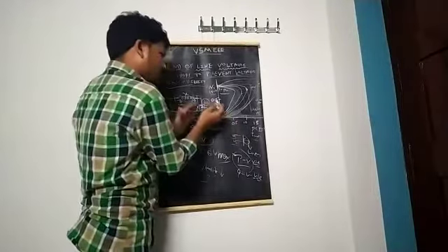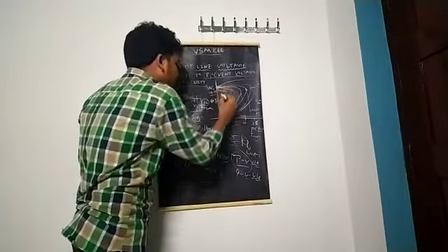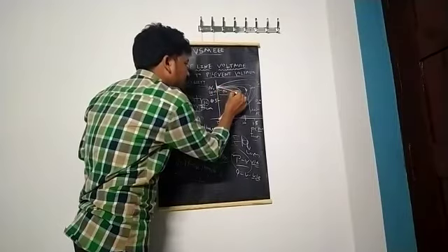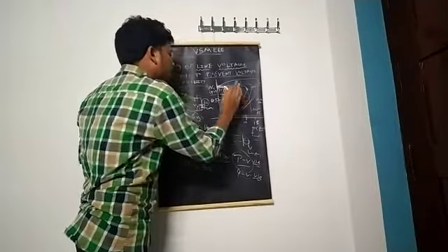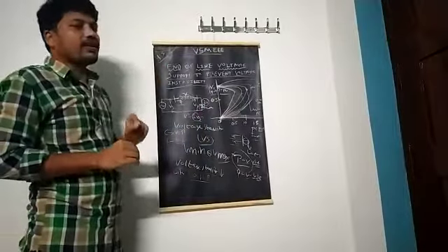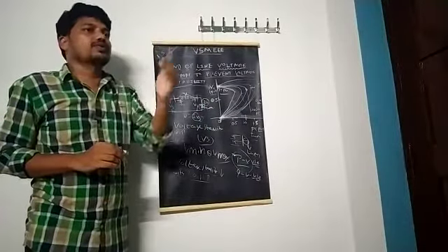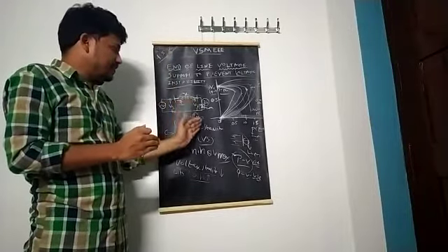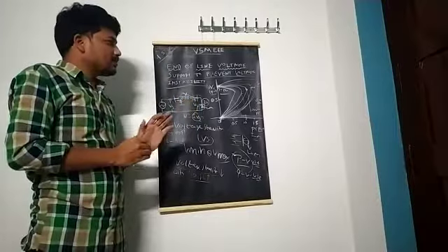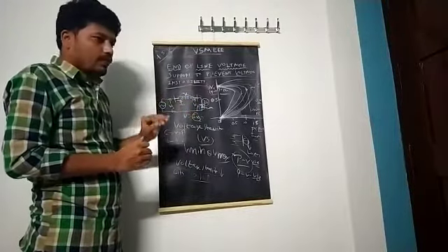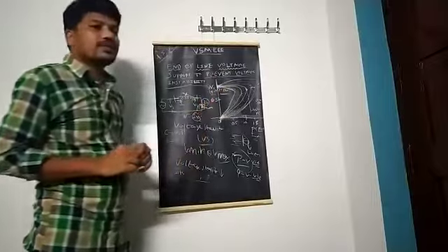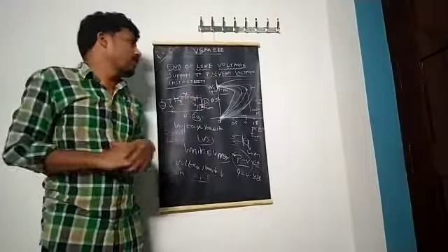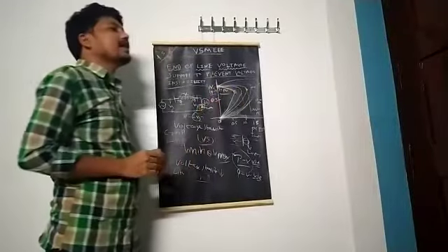So this is what we showed here in the curve. If P is equal to 0 and V is 1 per unit, and you are increasing the load from 0 to this point, the voltage decreases slowly. Is it clear? This happens up to a certain point. As P increases, voltage decreases while the impedance decreases and the current drawn by the load increases, up to some critical point. In some textbooks it is also mentioned as the nose point. This point we call the nose point or critical point.